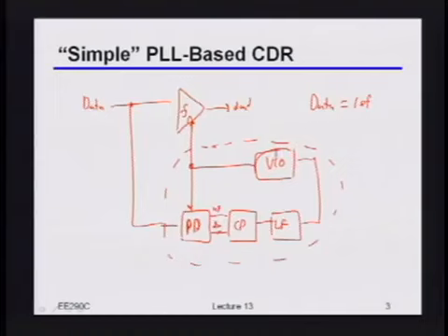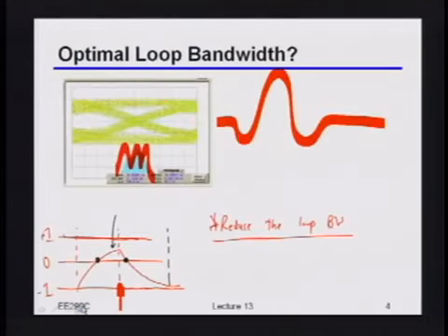And if it has quite a bit of jitter, that tells you that you'd really like to make the bandwidth of this loop kind of high in order to get rid of that jitter. But then the problem we started getting into was, wait a minute, if we make that bandwidth high, then unfortunately all of the jitter that's sitting on our incoming data, which tends to be quite a bit, if nothing else just due to residual intersymbol interference, gets passed very heavily into the output.